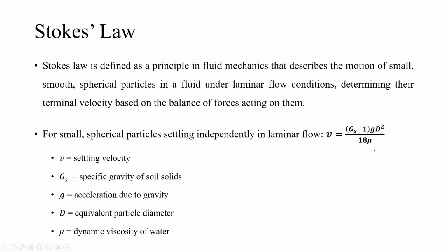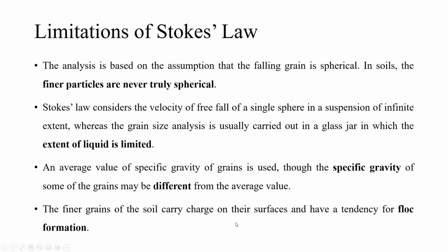The velocity v can be found by this formula: (Gs minus 1) g D squared divided by 18 mu, where Gs is the specific gravity of soil solids, small g is the acceleration due to gravity, capital D is the equivalent particle diameter which we are finding, and mu is the dynamic viscosity of water.